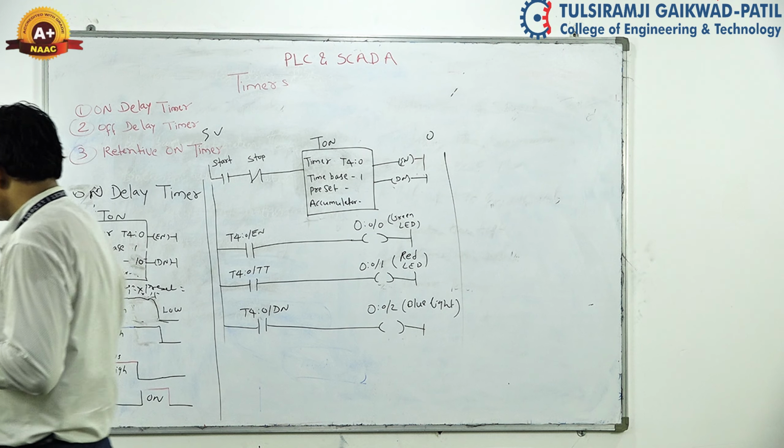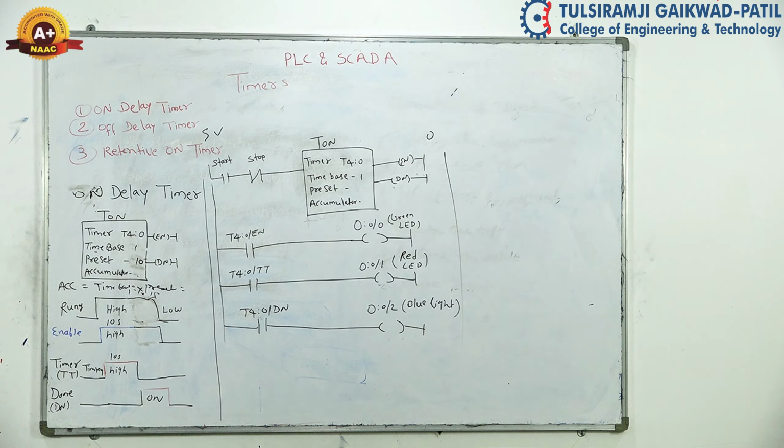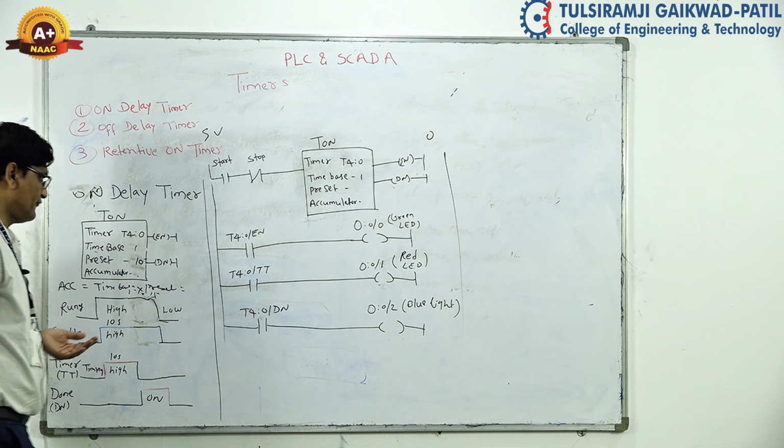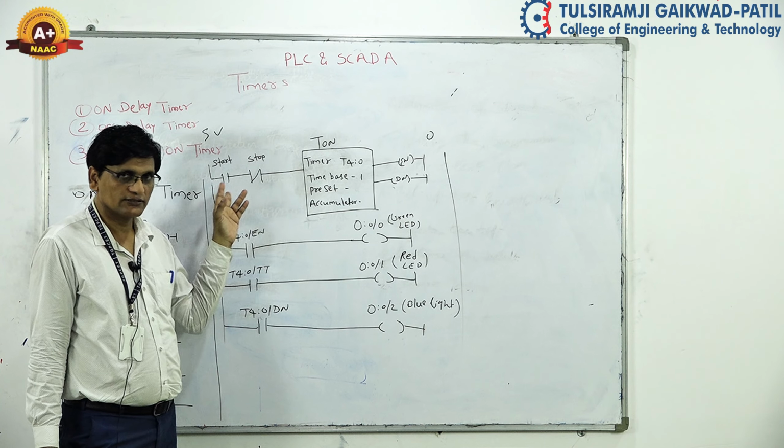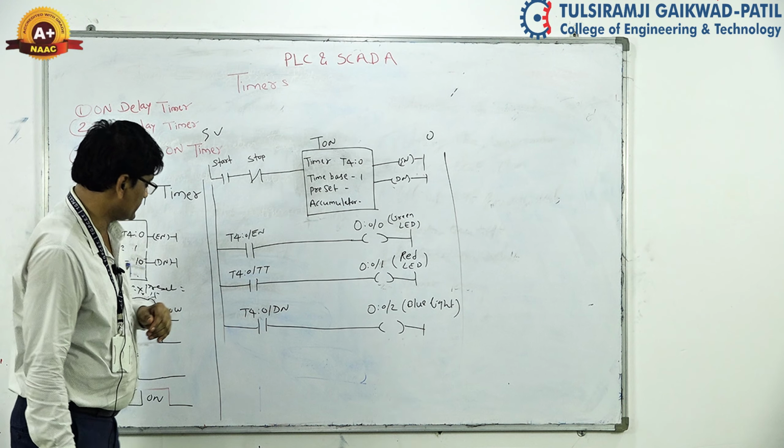rung of the ladder logic programming. That time again you have to start the rung by pressing some contact, like here we use the start button, stop button, like this.